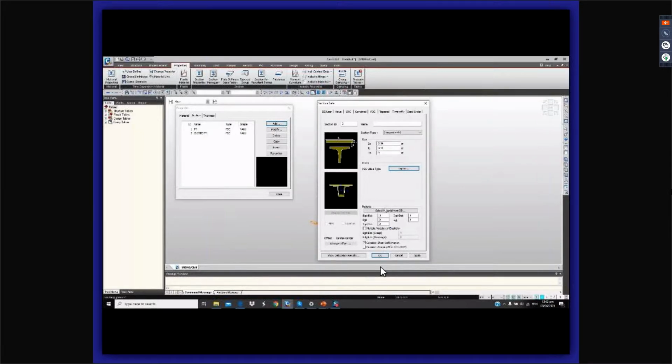So we have P4. We will need to select the material for the slab and the girder, so this is for the composite section to be analyzed as composite and non-composite. So let's get it from the AS 5100 database, for the slab C40, then AS 5100 as well for the girder C50. And click on OK, and then the modular ratio would be automatically computed. And let's change the offset into center top. Okay, then don't forget the name of the section. So this is composite P4, apply.